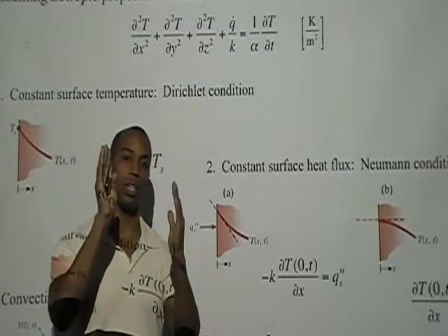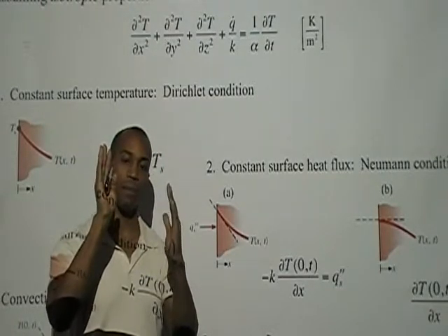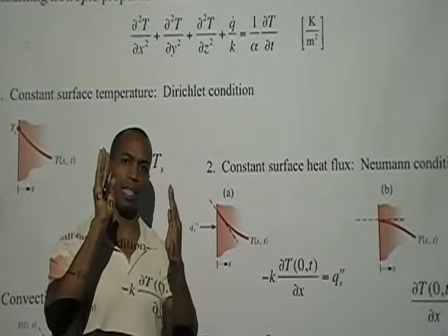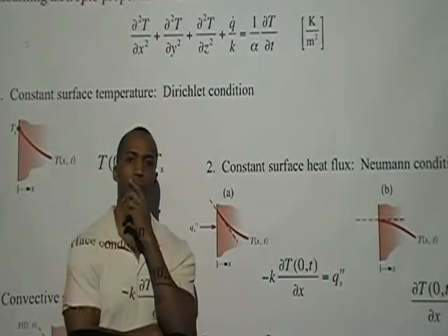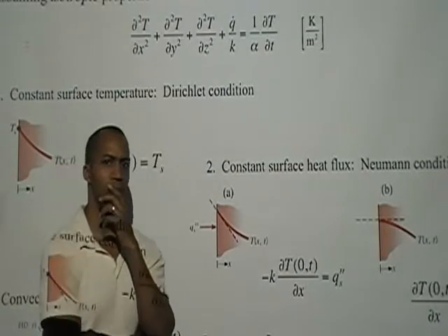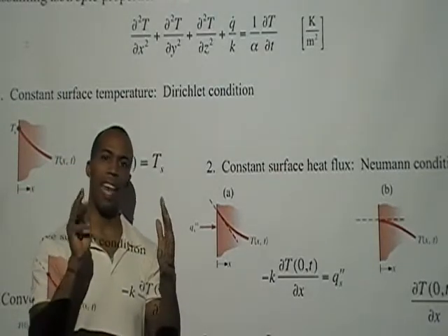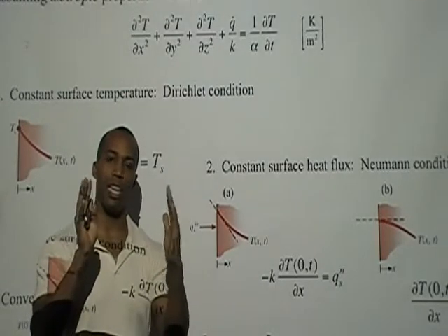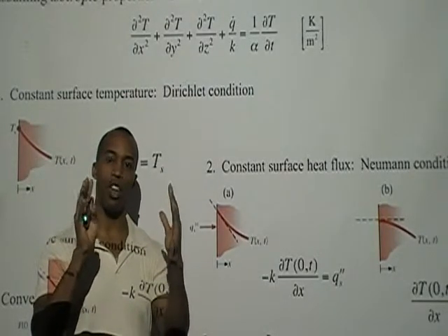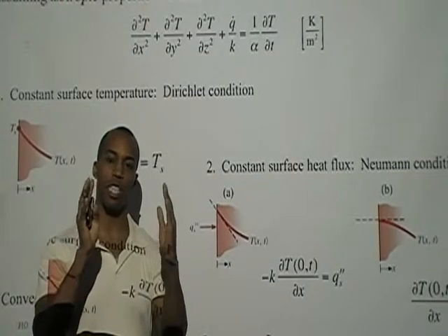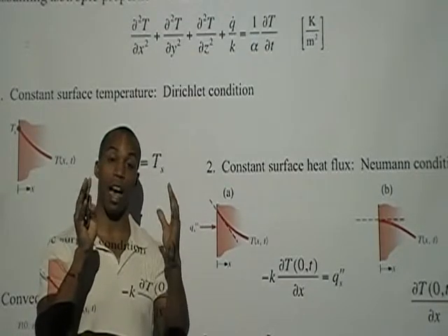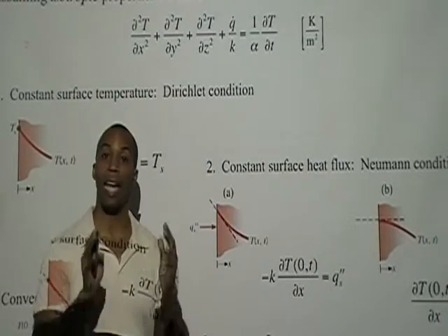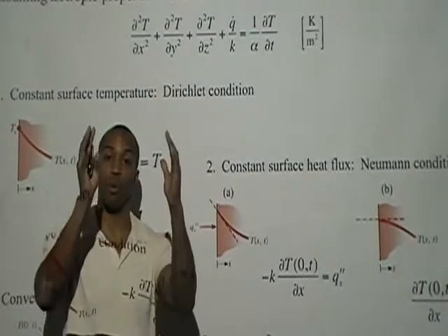The question I want you to ask yourself is, would you be able to determine the temperature distribution inside of the slab? So the thing is that in that situation, you have a problem where you're putting heat in, but nowhere in the system is there a temperature set that's defined as a reference in the system. Meaning that you really can't determine what the temperature profile would be in that situation.